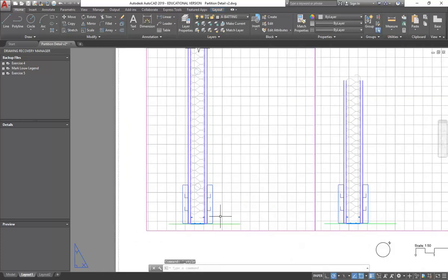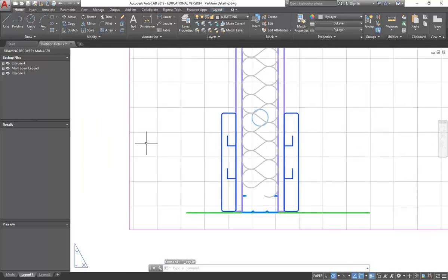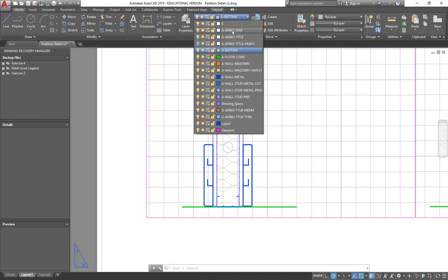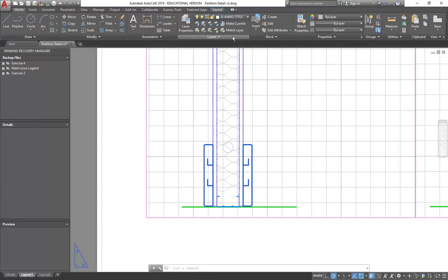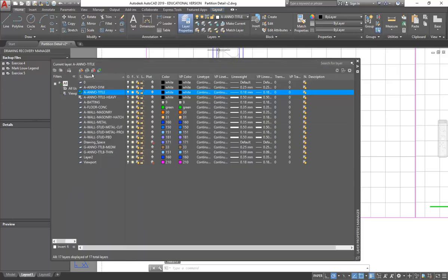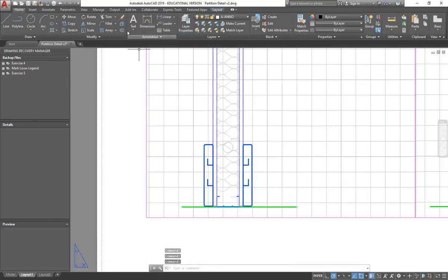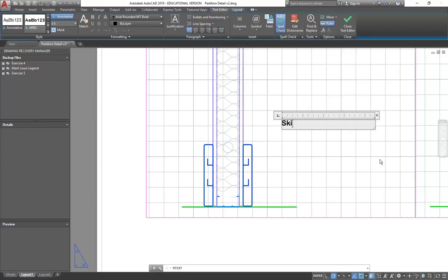So if I want to put some notes on in paper space, I don't need to do anything more. I'll go to my annotation layer. Now I don't have one for general notes, I've just got one for the title block, so I'll go and make a new one, just Anno, and make it the current layer, and just show you, of course, that if we draw some text, I'll do multi-line text, and so this might be for the skirting duct.